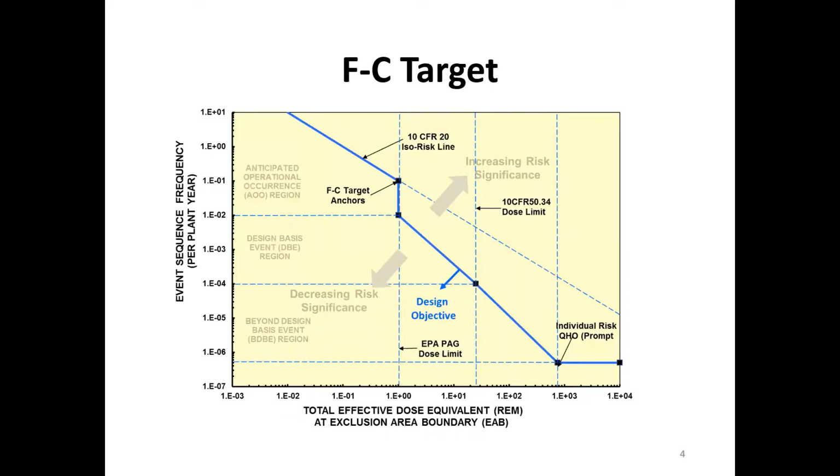Yeah. Also, Nilesh, because the dimensions of the structural elements, at least in the reactor building, are imposed by layout and radiation protection, the reinforcement is mainly fixed by the minimum amount of rebar. Well, in some cases, right? This may not be a good example, but if you look at several containments, there are questions of voids and constructability because of the congestion of the steel, particularly when you have a lot of diagonal steel because of the seismic design. Right.